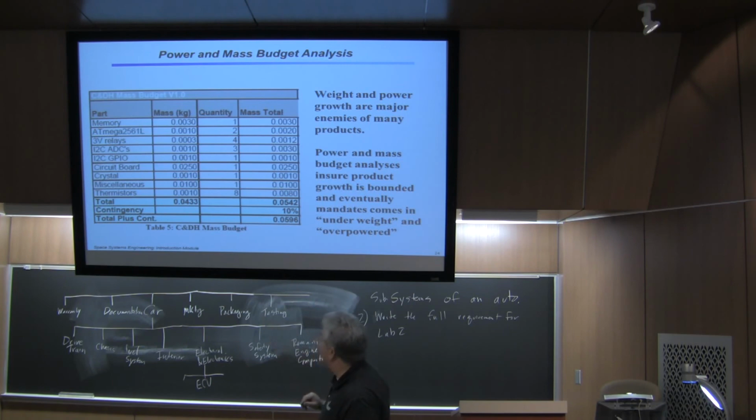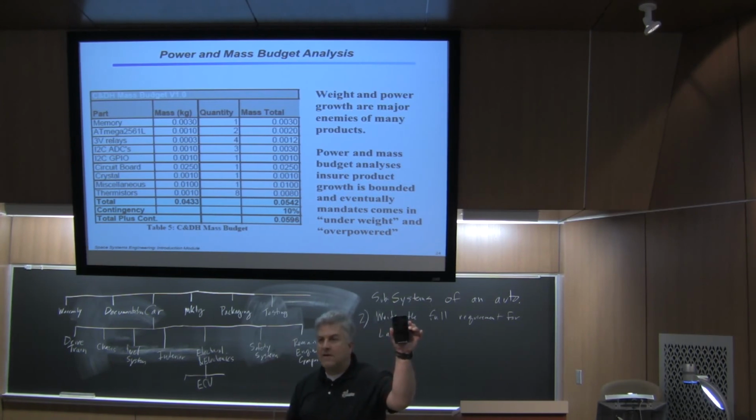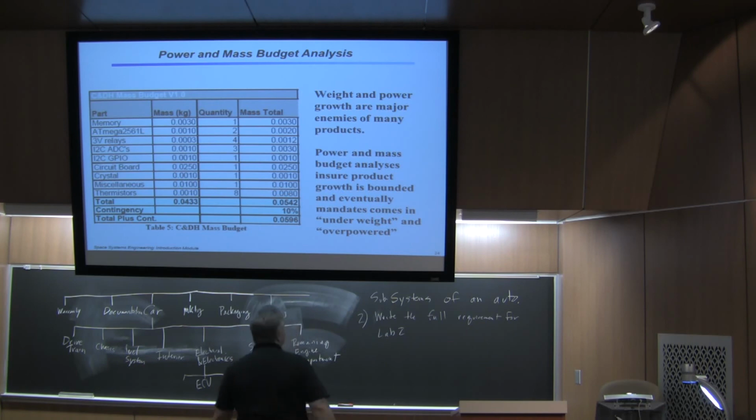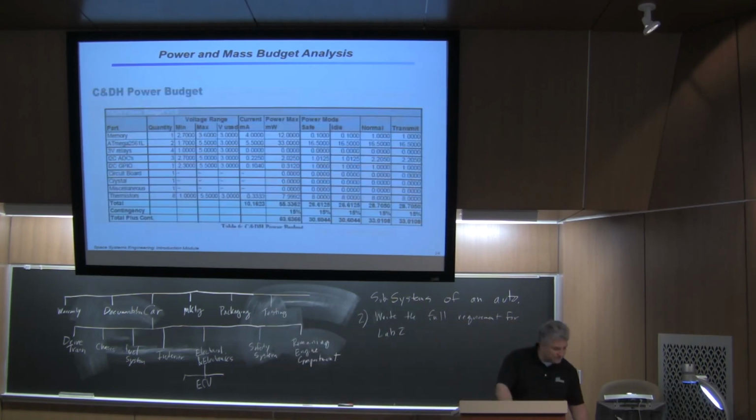You could say the same thing over there. The I2C is going to have to consume so many amps, microamps, or milliamps, and the microcontroller is so many microamps, and the safety circuit is so many microamps, and you have to make sure that you're not going to drain your battery so fast because you've decided that the LCD is going to be really high brightness, and it's going to consume so much energy that your battery has to be doubled in size.